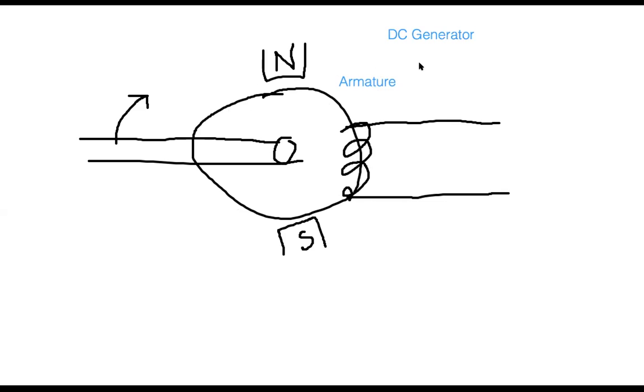But in the case of a DC generator, hardly 1000 volt is produced, that is the maximum. Typically 500 volt, 400 volt, even much lower voltage. That's why in a DC generator, the common practice is to rotate these coils. In other words, rotate the armature with the help of the shaft and keep the magnetic field static. This is just the opposite to the synchronous generator.